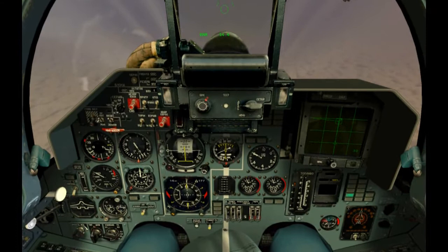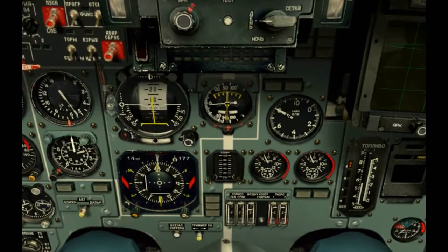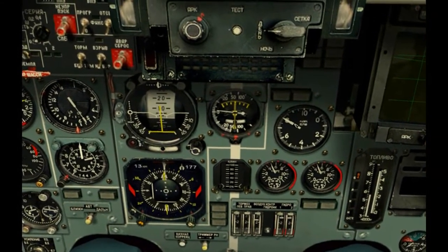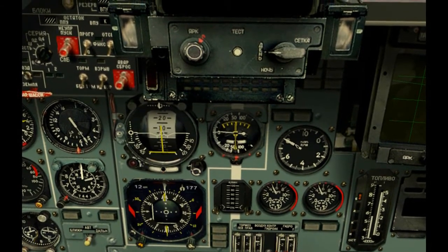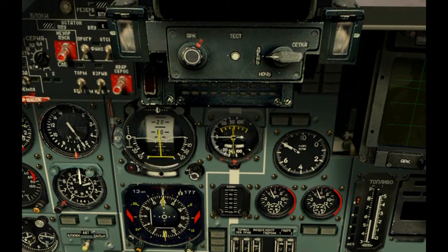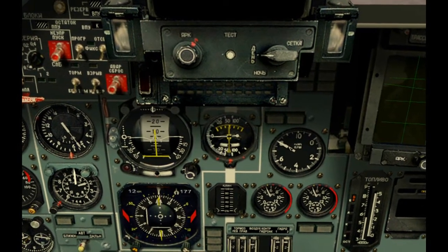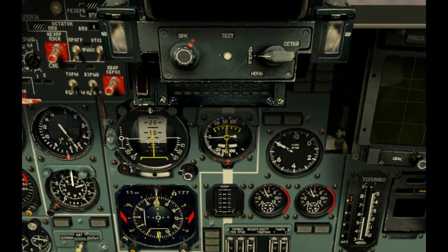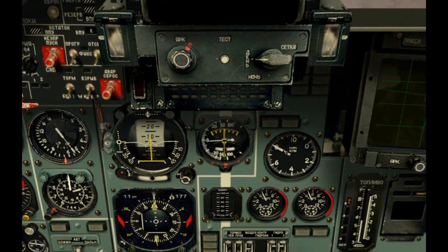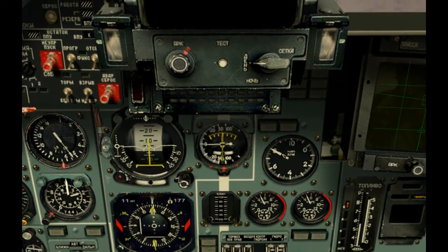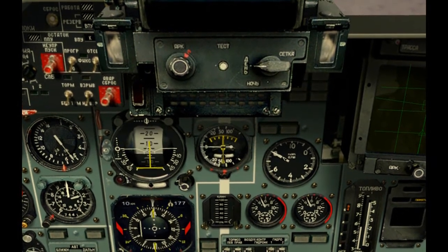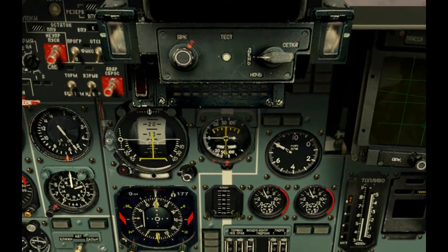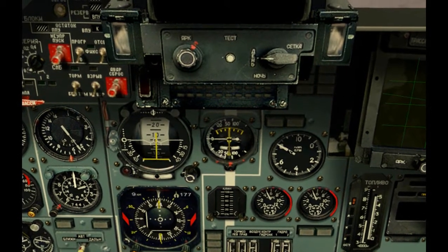Let's have a look at our panel. Notice that the ADI shows the same thing as the flight director circle in the HUD, except instead of a circle, it's represented by two yellow needles. The horizontal yellow needle shows us how we should fly to maintain altitude, while the vertical one shows us how to fly to stay on course. By putting the circle in the aircraft symbol right on the cross of those two needles, you can fly at your assigned altitude and course.